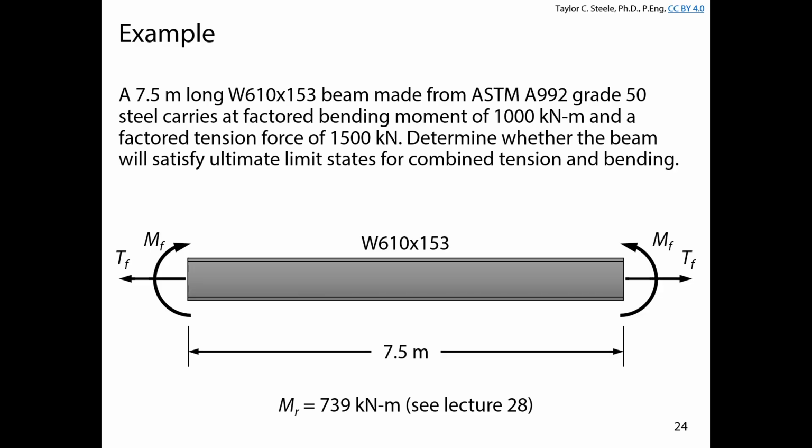what happens here. This is going to be important to make sure we get the units right here. I'll just write everything in Newton millimeters. That'll keep me straight anyway. So we've got 1,500 times 10 to the 3 newtons times Z. Z is also something we need to look up in the handbook for our section. Z is 4,600 times 10 to the 3 millimeters cubed.